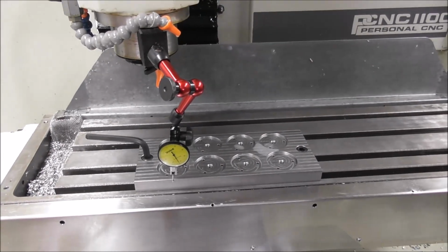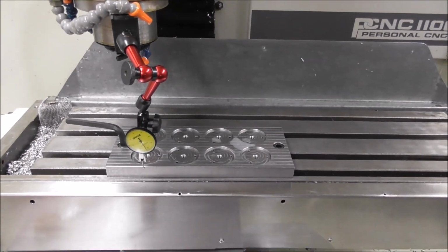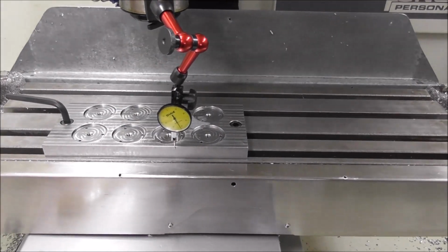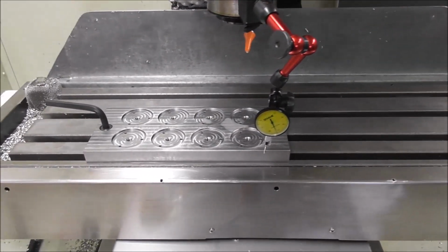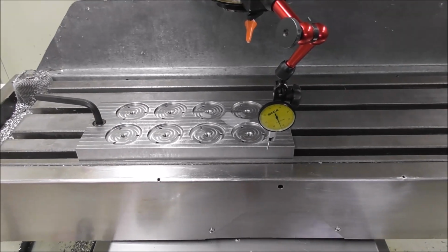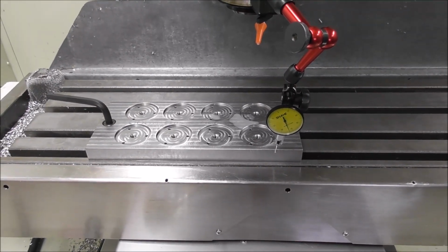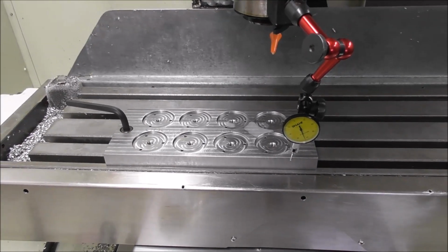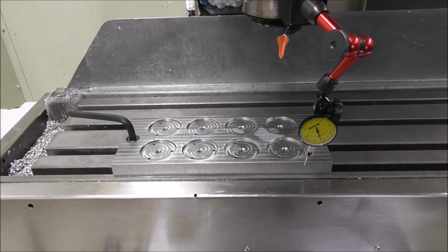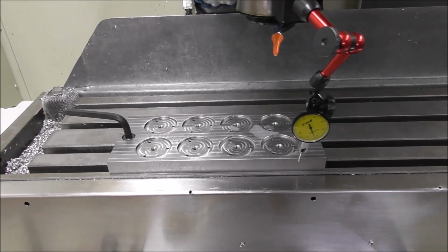Okay, so you've got a fixture with a couple of T-nuts, a couple of cap screws. Doesn't take a second to dial it in. You could put some keys underneath, but they're never highly accurate. You could hold it in the vise, but then it's up high in the air. And the further it is away from the slides of the X and the Y, the less rigid it's held and the less accurate it is.